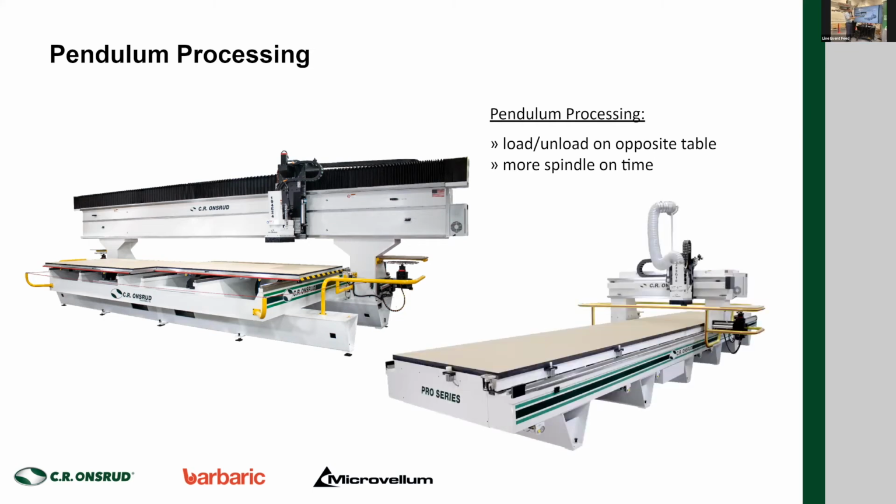We can also do this on our long gantry machines. This is a 20-foot gantry machine here. So you load the 8-foot sheet up here at front, in the front. The gantry will start cutting on that one. Your operator will load the next 8-foot sheet at the back of the table. And then the gantry is what's doing the pendulum processing. So we can do that on moving table format and gantry format.